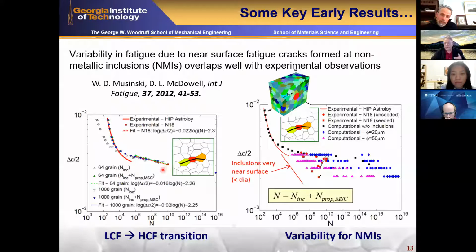In other words, it's the heterogeneity, the spatial distribution of the driving force amongst grains in a polycrystal that establishes this transition to a shallow slope. So really, we have these empirical, well accepted laws of fatigue, but then when you do the microstructure sensitive fatigue, those laws sort of become emergent results from the underlying small fatigue crack formation and growth relations.